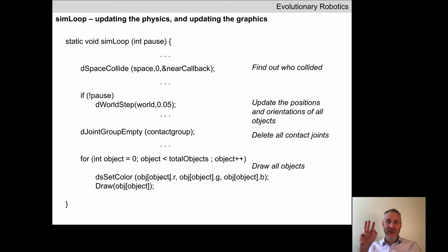There are actually three aspects to time that you need to think about as you continue creating your simulated robots. The first is the number of time steps. Some of you may have num time steps set to 1,000, 10,000, or 100. That's how many moments in time we're going to simulate inside your world, so that determines the total amount of time that elapses in your physics engine.